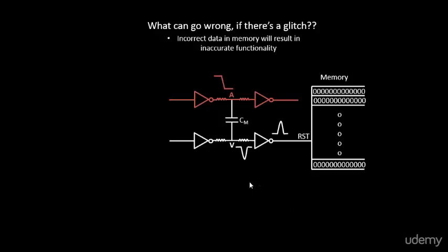That's why the glitch has become an increasingly important factor to be considered while doing clock tree building, while doing VLSI design, while doing physical design, while routing. This particular phenomenon has become an increasing point of concern for all VLSI engineers, and all of them are working towards it. So shielding is one of the techniques that will actually protect this particular victim. Shielding basically says that we put a wire over here, and these wires are connected either to VDD or ground, because VDD and ground are the ones which won't switch. As a result of that, your victim is protected.